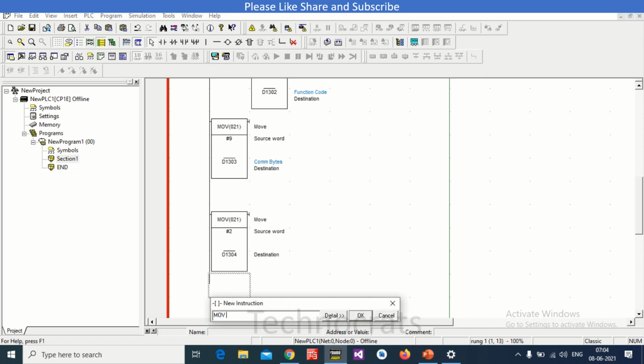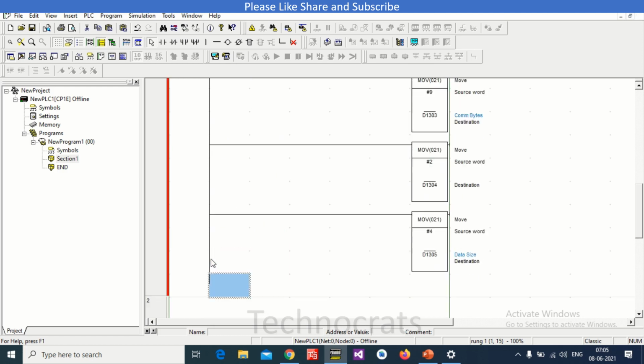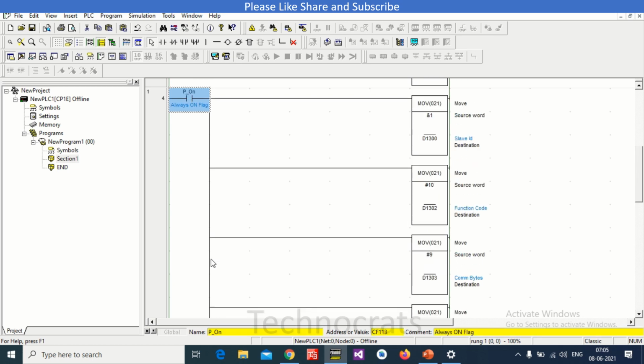MOV. Now D1305 is for data size in bytes. So how many bytes we are sending to the controller. We are using 4 bytes here, so we use #4 to D1305. This is your data size in bytes. Okay. Now after this, D1306 onwards, this is your main part. This is always on here.